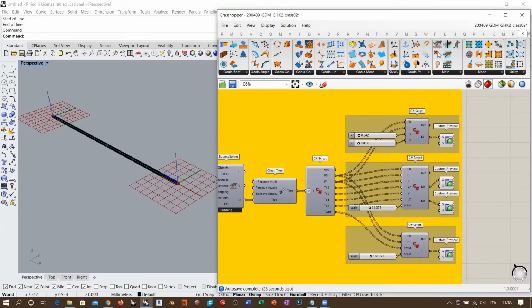Okay, I agree. I was just missing that part of the explanation, and the other part that I missed is you mentioned the difference between the support and the anchor. Very quickly, supports are meant to work with rigid bodies. So supports only work with things that are defined inside this group of components, 6 degrees of freedom, while anchor points work basically with any vertex. So you can, for example, use an anchor point to anchor a rigid point set. Yes, you can do it. Can you use a support to anchor, for example, the extremes of an elastic line? No, you can't.